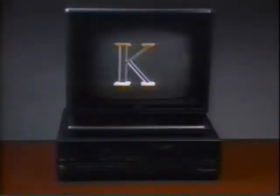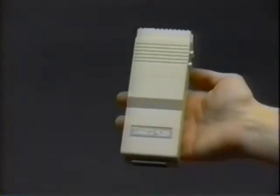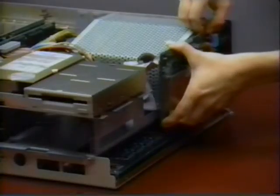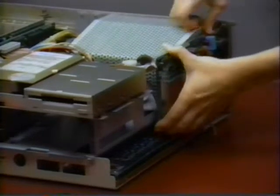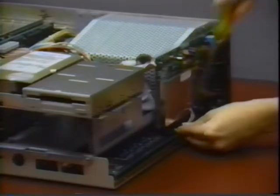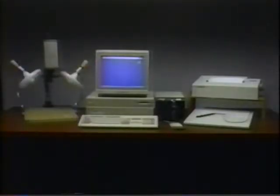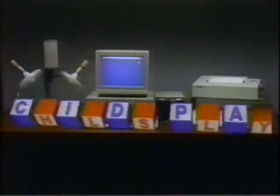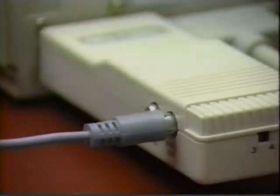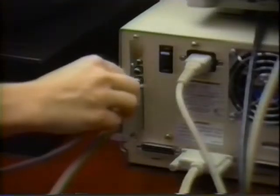Amiga graphics can be recorded onto videotape by using an Amiga 520 video adapter connected to the Amiga's RGB video port, or by sliding an Amiga 2300 Genlock board into the internal video slot. The Genlock feature of the 2300 allows Amiga graphics to be superimposed over any incoming video source, such as a camera or a second videotape recorder. An RCA to RCA cable is used to connect the video out on the 520 or 2300 to the video in on a VCR.